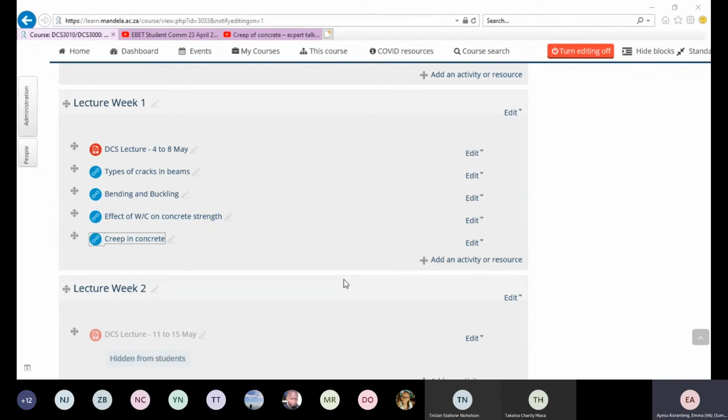the particular structure. So if you look at something like a beam, once you place a load on that beam, the load on the beam causes the beam to bend. If you release the load, the beam will attempt to recover and get back into its original shape. That would be the elasticity or the elastic deformation that we're talking about. If you look at something like pavements, or even floor slabs, if you place very big equipment onto a slab, once the equipment is removed, after a while, you'll see that there's a bit of a liftment of the surface. So though there'll be a dent or some sort of deformation, it will almost start to recover by itself, though it will not get to its original shape.